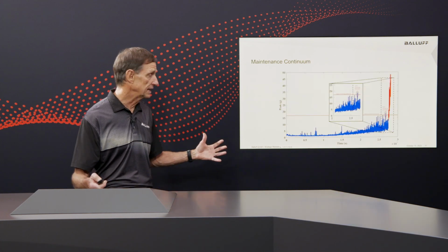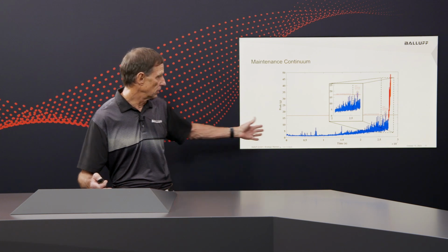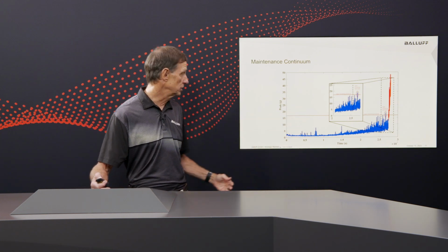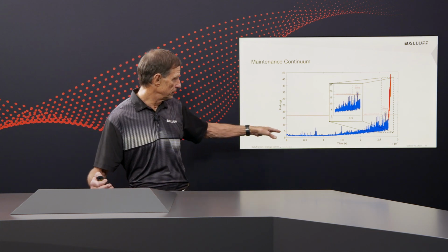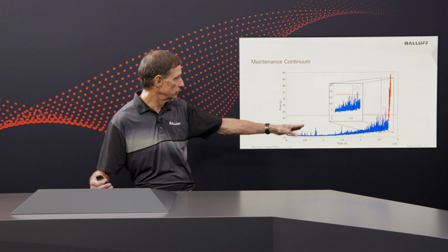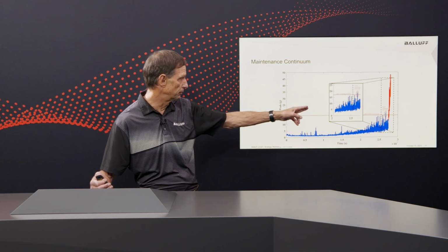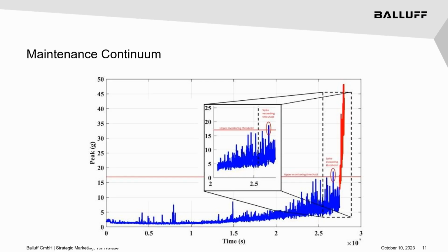So what does this look like in reality? We have here a graph of vibration data on a machine over the period of about a year. As you can see, the performance is relatively stable until we start to go towards a failure and a breakdown, the red part of the curve indicating a catastrophic failure. We've highlighted a period of about 2 months of data here where you can start to see things start to move out of spec, but not yet quite into the failure mode.